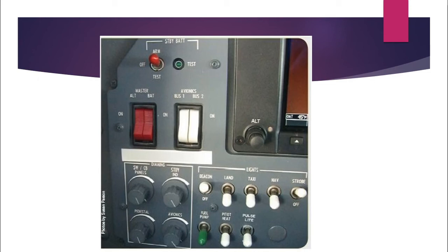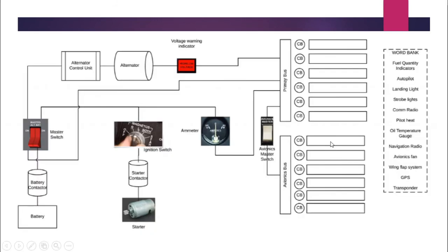It's basically an extra protection against problems with the electrical systems. Especially when you're starting the plane, you're starting the battery, the starter. If something's not connected properly, you don't want a whole bunch of electricity just willy-nilly going through your radio and your GPS and autopilot. So that's why they have an extra switch in there to protect those systems.